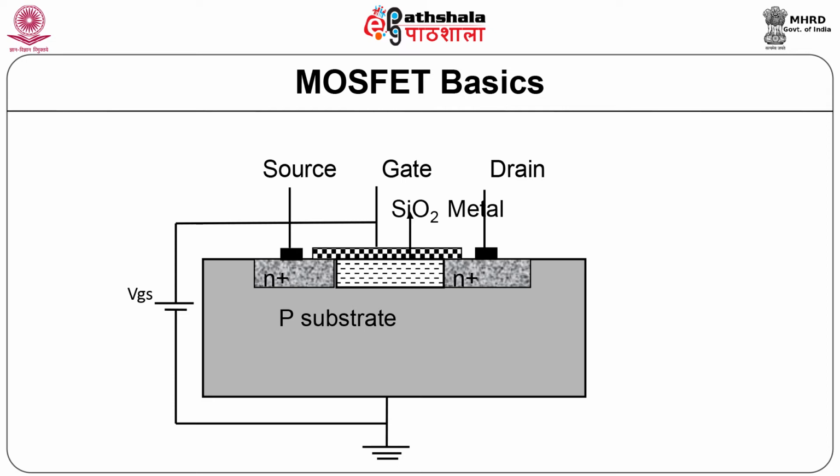An increase in the drain voltage increases the drain current, producing resistor type operation for small voltages, similar to a JFET. Pinch off occurs when the drain to source voltage is sufficiently large, which reduces the field near the drain to 0 and makes the drain current relatively constant.